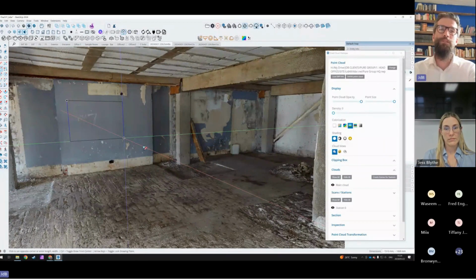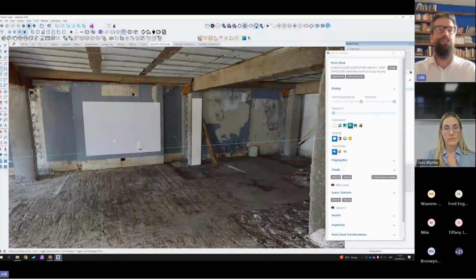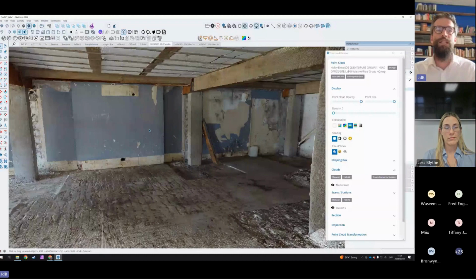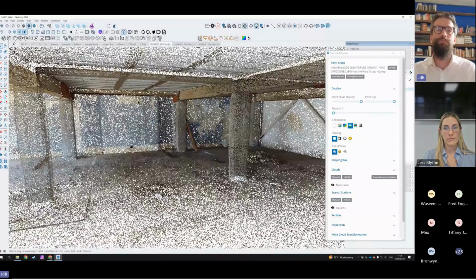And as I draw that rectangle, I can start drawing out the walls, I can start drawing out the columns, and I can snap to all these various shapes and spaces to draw these various elements. And as I mentioned before, the client in this environment was really struggling how to contextually create the interior design with these columns in mind.